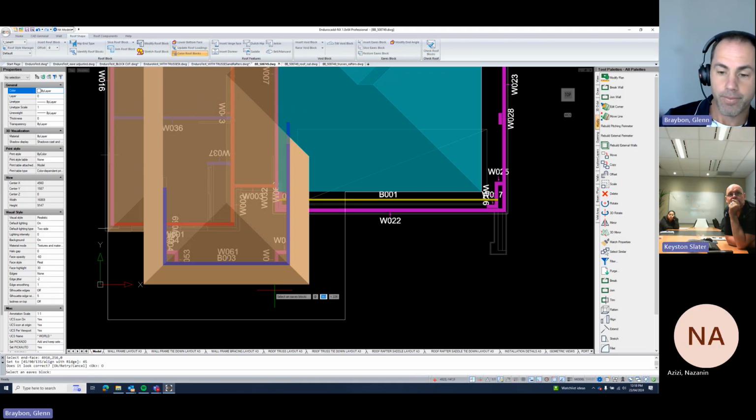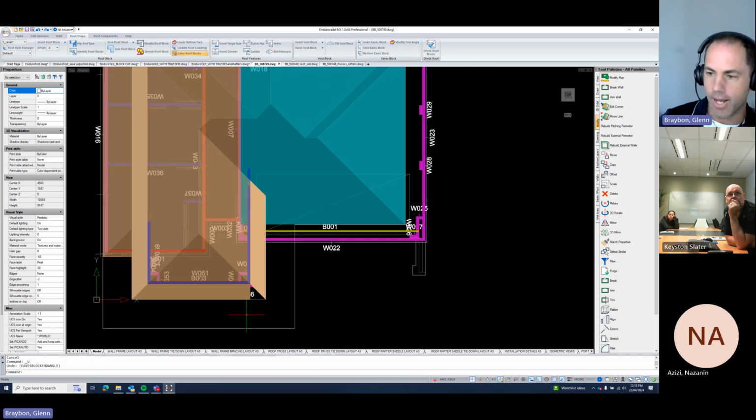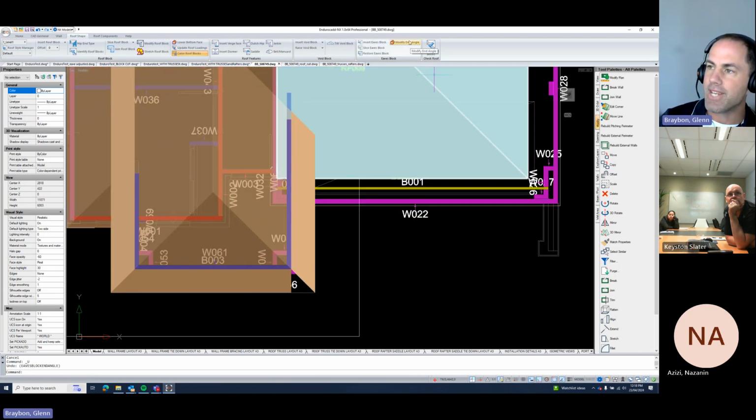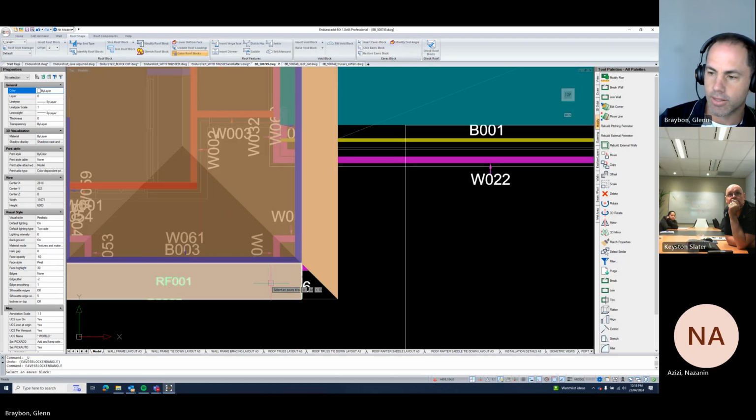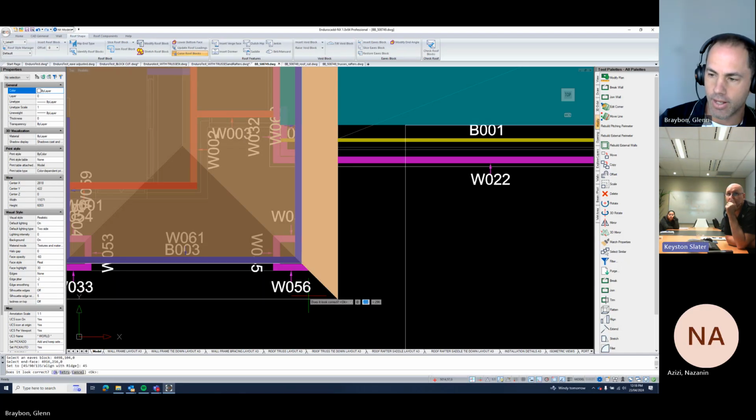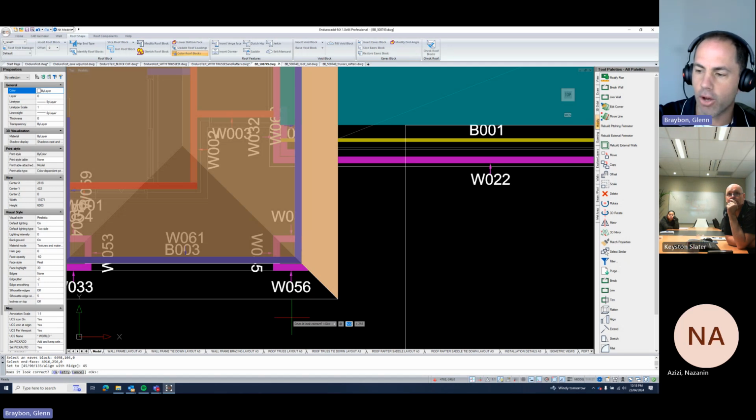To change the end angle, did you just do a right click? Yep, so we'll just go back. Okay, so modify the end angle up here in the eave block menu. Can you see the mouse up the top? Yeah. So we're just going to modify the end angle of the eave block. Then it's select an eave block, select an end face, which is obviously left clicking. And then set to 45. And then does it look correct? We can see the okay, which should be yes, and it will be changed to yes, hopefully by the time you get it. But at the moment it says okay.